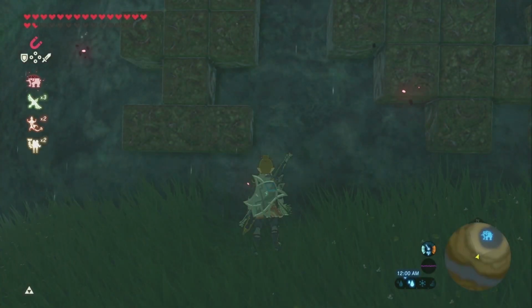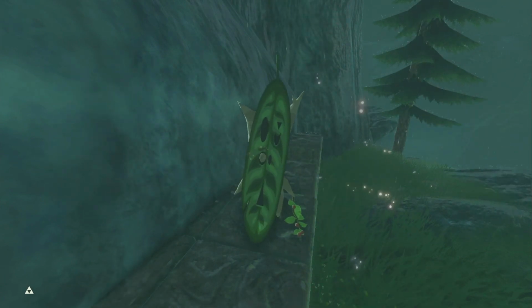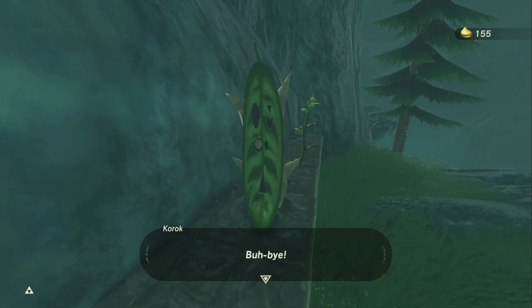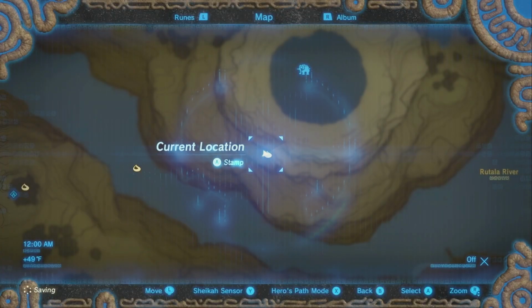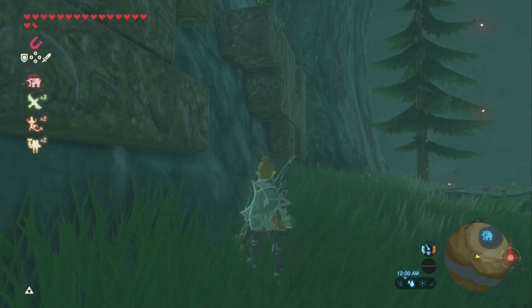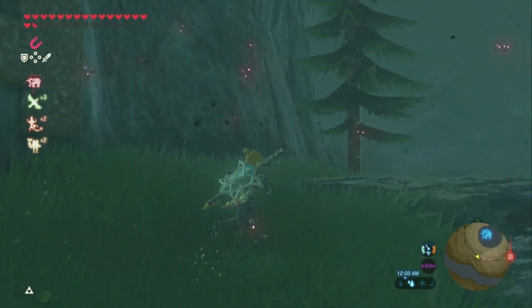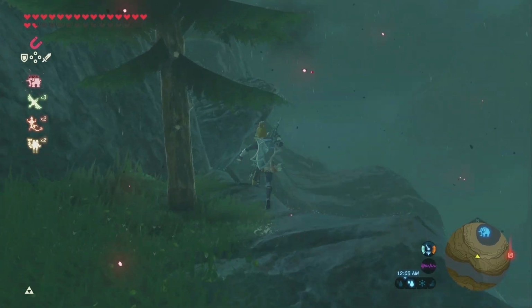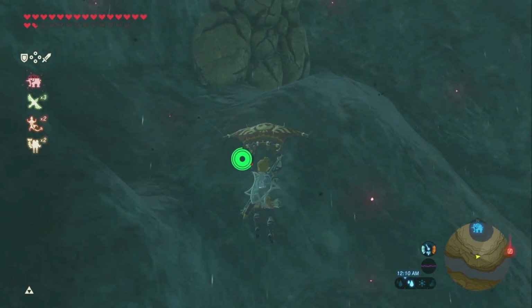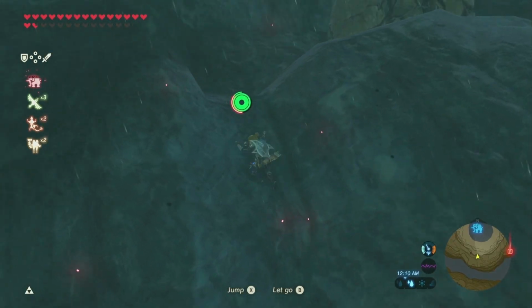The arrangement should include a check valve so that when the pump is at rest, cold water from the inlet pipe cannot flow backwards through the hot water circulation loop. If the pump is inoperative when we turn on a hot water faucet, we will get water flowing both from the water heater and from the cold water pipe through the return side of the loop.